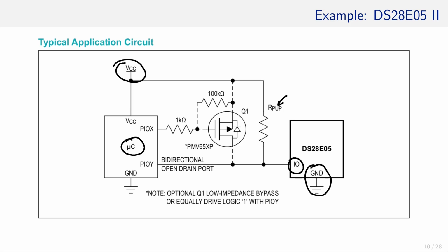Therefore, if the line I/O is not in use, it idles high, like the wire that we have seen earlier in the session about DHT or in I2C or even UART not too long ago. Since it is charged to the VCC level, it is used to power the EEPROM. However, when communication is commencing, at one point in time, the master is going to pull down the wire to the ground to transmit some data. So the EEPROM needs to have some sort of method to bridge the times when I/O is 0 to remain powered.